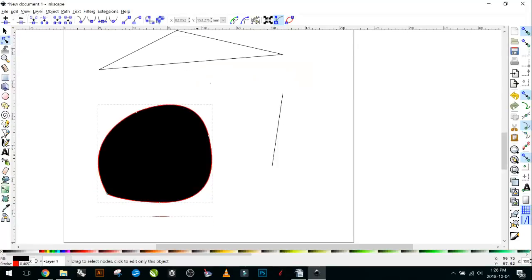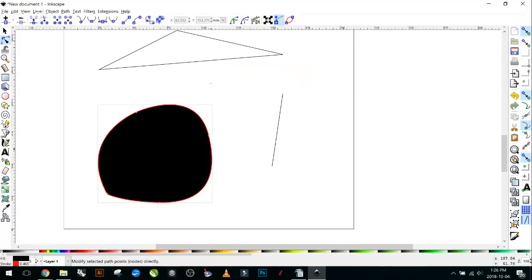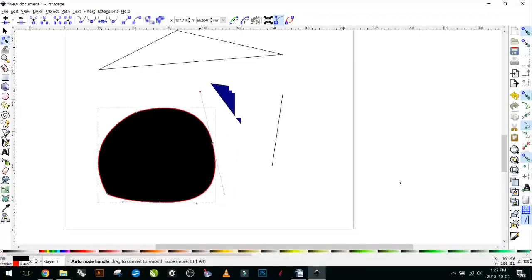Come here and click on a different shape, and for curves you'll see the nodes go to where we stretched our lines out using our Bezier curve tool. So with these nodes, if you click on a node that's on a curve, you'll get these things called handles. And all these handles are, so we can move our nodes around, and that's great, but the handles will allow us to adjust our curve size and angle, like so. And of course you can do this for both sides. So to get those handles to pop up again, just click on the node using your node selection, and you can then adjust your handles from there.